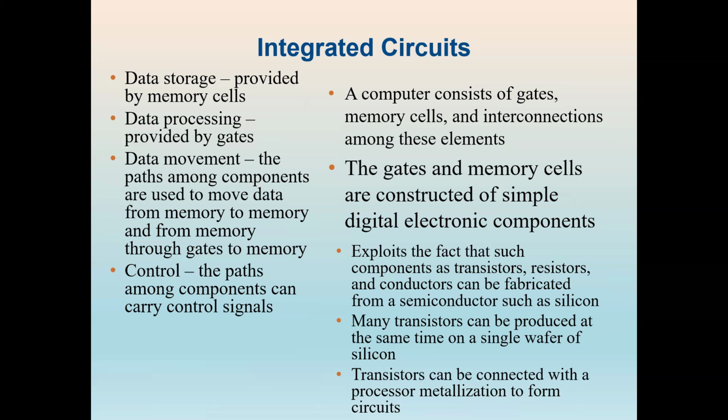So let's say, for example, a gate will have 1 or 2 data inputs plus a control signal input that will activate the gate. Now, when the control signal is on, the gate performs its function on the data inputs and produces a data output. Now, when the control signal is off, the output line is null, such as is produced by a high impedance state.